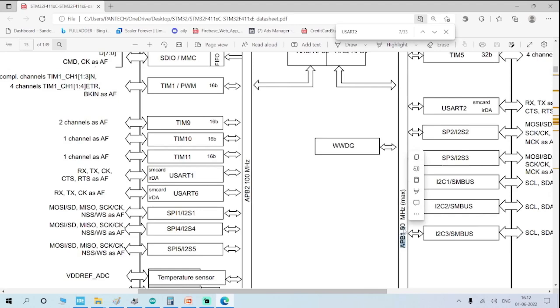Either you just open the software and download an empty code, and you could check out these special function registers on the emulator. That's one way. The other way is to use the data sheet. I suggest you use the software version because it's much easier. Else you need to correctly add the offset value to get the right value of the register.